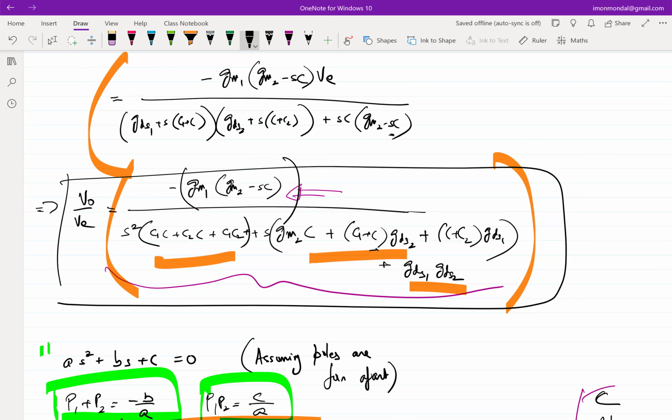So that's why people tend to increase the values of GM1 and GM2. Tend to size GM2 in such a way that the phase lag associated with this extra zero is negligible, because the zero frequency, as you can see in this case, is at GM2 over C. Right? So C is the Miller capacitance of the Miller compensated op-amp. So you have fixed the Miller capacitance. If you have to push the zero to a higher frequency, you have to increase GM2, right? So that's how it is.